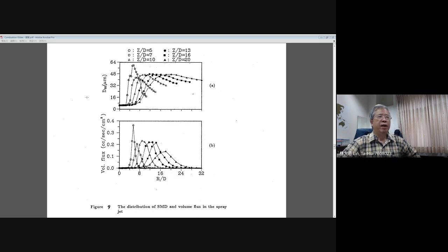Actually, it involves the total heat release rate compared with the gasification strength. Total heat release is based on the volume of the droplets, but gasification depends on the surface you have. If you have a large liquid surface, then you will have strong gasification. We bring these two factors together to give you a very nice typical identity for spray. We use the Sauter diameter.